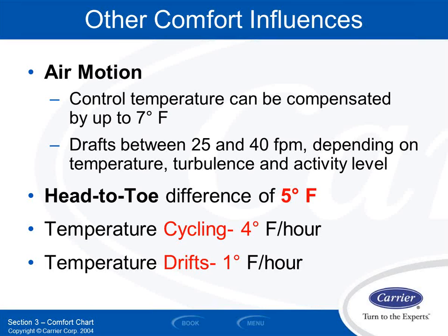There are some things that happen with that, both in terms of just physics as well as in terms of standards and codes. The hotter the air is coming out of the diffuser at the ceiling, the more likely that air is to stay at the ceiling, right? Because we already know that hot air is going to rise. I rely on my diffuser and the orientation and directional turning vanes on there to throw the air down into the space. Well, if the air is really hot, my diffuser can't throw it down as easily, and the air hugs the ceiling. There's actually a prescribed rule for this, but it's been in the ASHRAE handbook since the 70s. It's in ASHRAE standard 55. It's in ASHRAE standard 62.1, which is the ventilation standard.